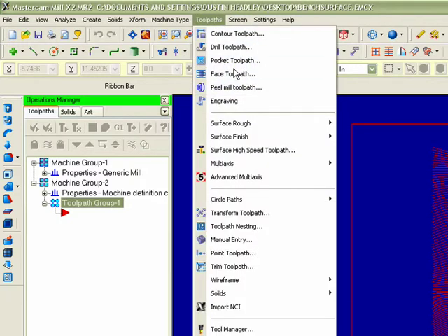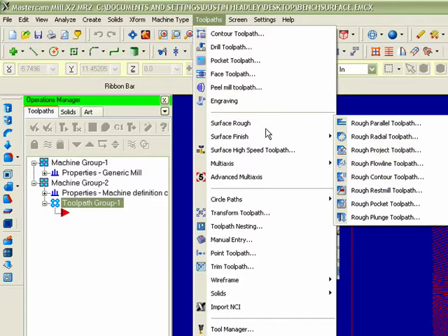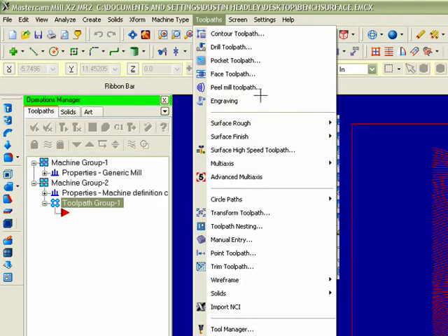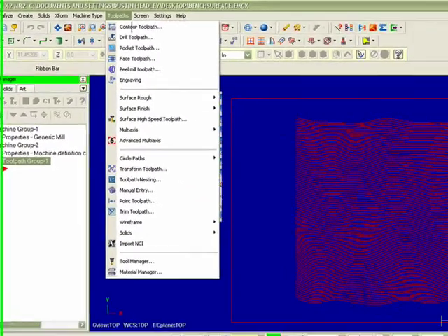Now here, in the toolpaths window, we have two sets of operations that you'd probably be concerned with. This set of operations is working with vectors, and this set of operations is working with surfaces. Essentially you're going to be exporting geometry from Rhinoceros, either surface or vector data, and you can use these two to do that. Another tutorial will go over the surfacing of this, but let's just go through the contouring portion of this. Depending on what you're doing, obviously you're going to use different things. If you want to clear out an area, a pocket toolpath would be more appropriate, but I'll let you explore that on your own time.